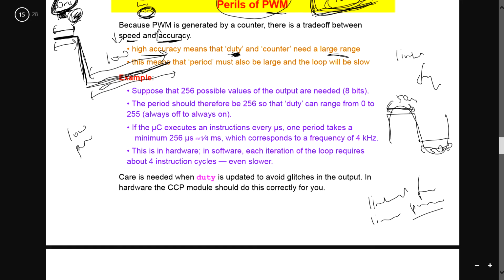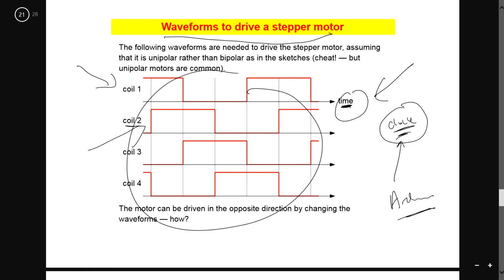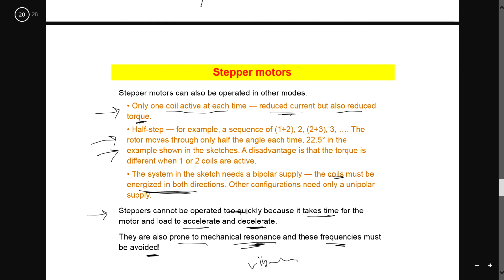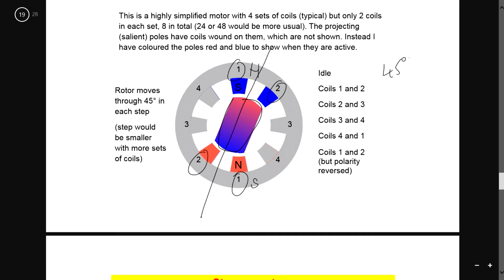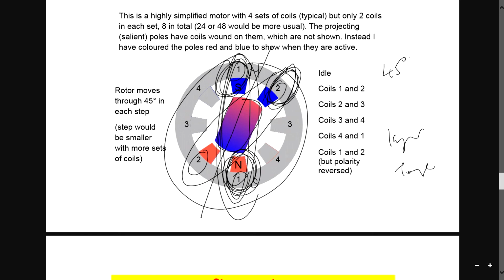And nonetheless, when you turn a motor, you can use the waveform method to drive your stepper motor, so that you can drive your motor like this. If you connect using two coils, as I said, two coils provide a much larger torque than using one coil to spin your motor. So it depends on your conditions. If you want a large torque, we normally recommend you use two coils, two sets of coils. This is the second set.